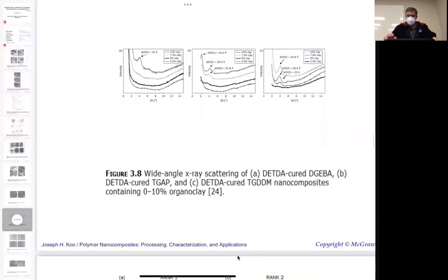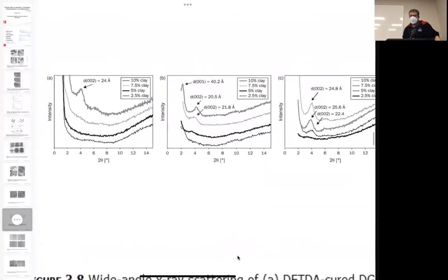All right. So in this case here, we can tell immediately on our system what we have. This is X-ray scattering, wide angle X-ray scattering. You start with, this right here is your solid surface, usually aluminum or something. And then as you come out, if you have an amorphous system, you're going to see no periodicity, no order.